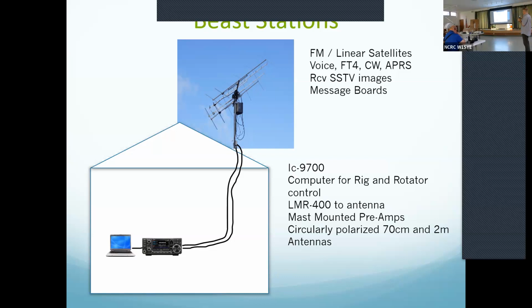Are those RF sensing, or are you doing something else? The preamp circuit on the IC-9700 cuts out when you key in. All right, so you're not building any RF sensing into your stuff. No. But I do have ones that can be triggered by a bias T and/or external 12 volts. So my EME one is on the sequencer. I send up the signal when it goes on, and then when it goes off, I turn it off. Plus I link it into the IC-9700, so it's definitely going to be off so I don't fry it.